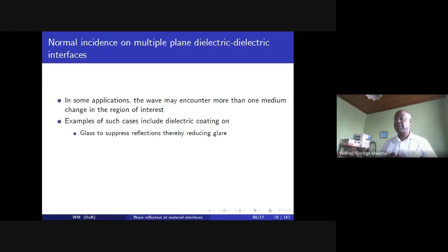So what we'll see is that in many cases, we can coat the glass at the top with a material with a different refractive index or dielectric constant, with a given thickness, such that the intrinsic impedance of the glass covering of the PV cell is converted into an impedance that looks almost like that of air.